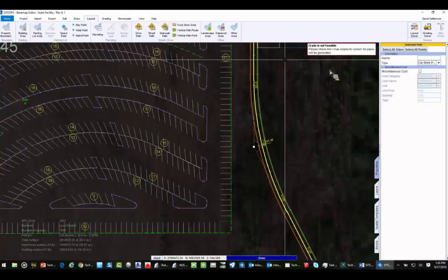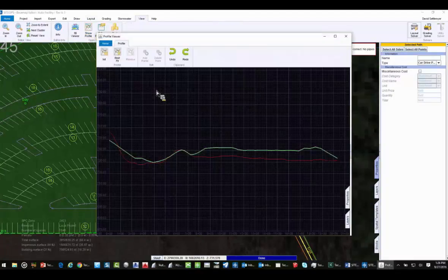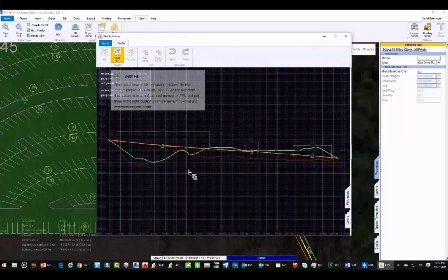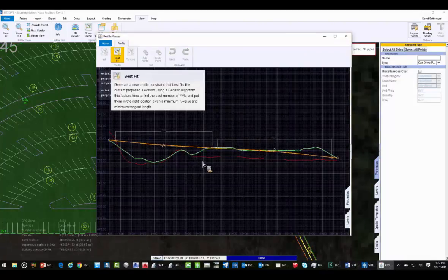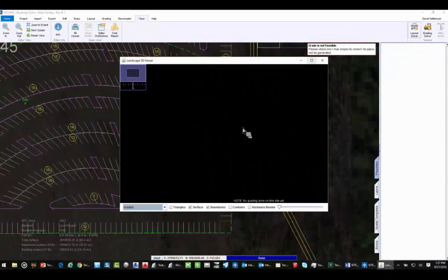So again, even though you can quickly draw things, you do have control. Because one thing you're going to definitely need in plants is control. Do I have buildings with relationships to each other? In this case, SITEOPS is finding the cheapest way to build the road. We don't want that. So I'm going to come in, put a 1500K value, and tell it, give me something that looks a little better that meets requirements. So it looks at that. How can I then optimize that roadway? I can add points, take points away, modify that, hit my layout. Let's grade it.